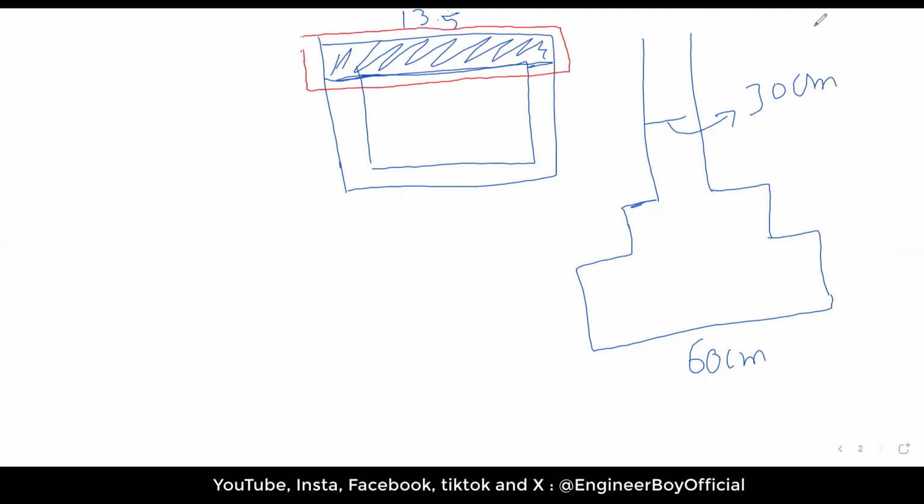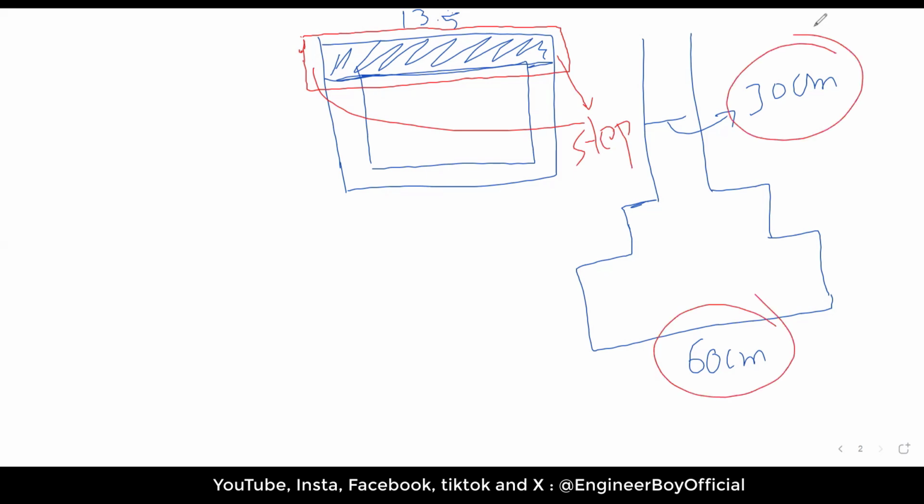It means we have increased the length for the foundation. How much are we increasing that? That's the point. That is just this step, and for the other side, we have just added these 2 steps. And those steps can be determined if you subtract the wall thickness from the width of the foundation.